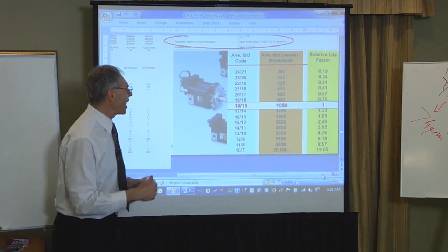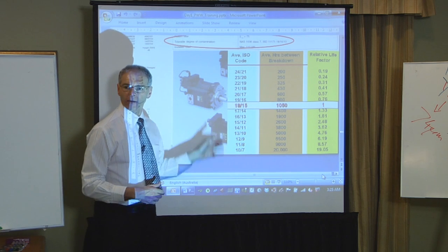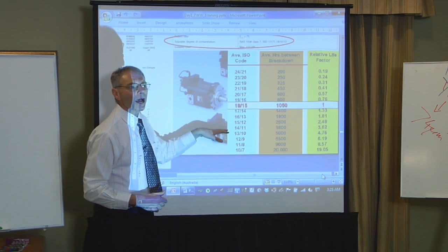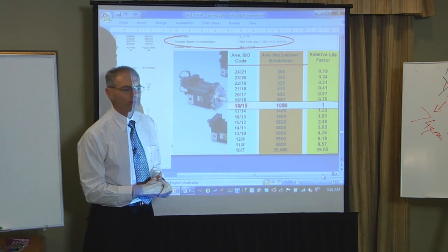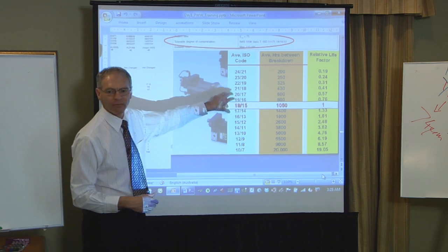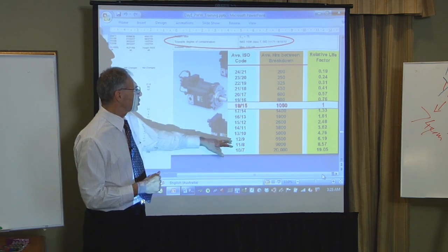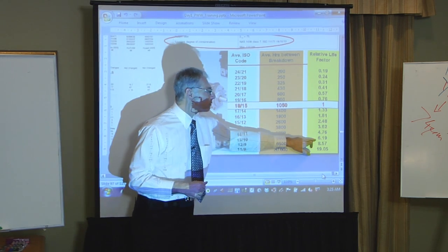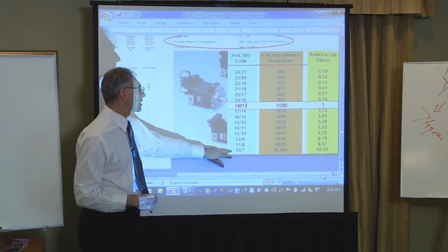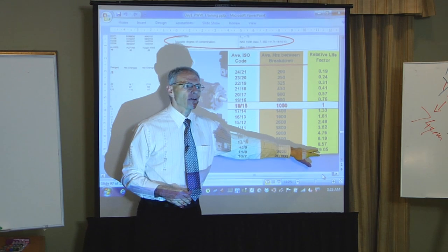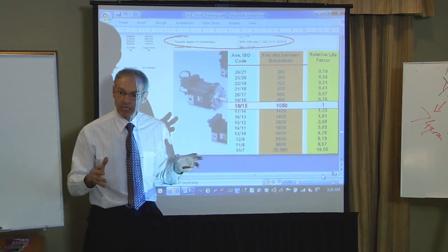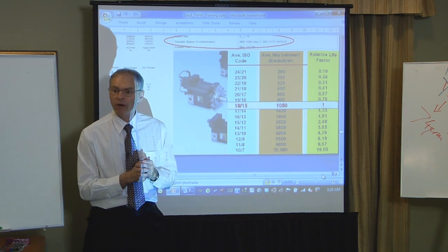And what that's saying is the cleaner you have your hydraulic fluid, the longer you will have between failures, because the wear particles that cause the failures are not there to cause the breakdowns. And if I get down to 12, I will get 6 times the life. Get down to 10, 19 times the life. And nothing's changed, the same machine, but now very, very clean oil.